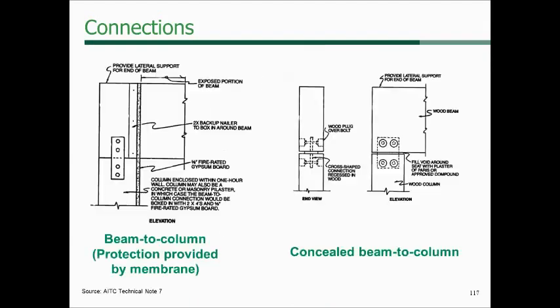And another one that shows we have a wood member that's coming in and connecting, wrapped around. This kind of shows it as if it's through the wood member or the wood beam, but actually the gypsum, I'm sorry, is wrapped around the member, 5/8 Type X drywall around the wood member. The assembly behind this gypsum board, with the gypsum board preventing any fire from penetrating through, protects these side plates.